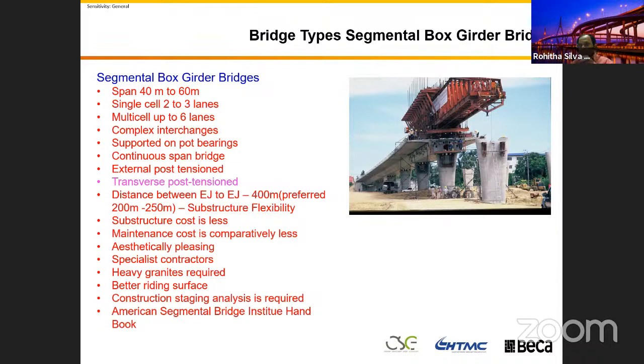We put that post-tension in here that provides the moment in the opposite direction. This simply supported one provides sagging bending. Your post-tension will provide hogging bending, then it is balancing out. That's how they design, because it's not rocket science. It's very simple mechanics you learn in your unit.